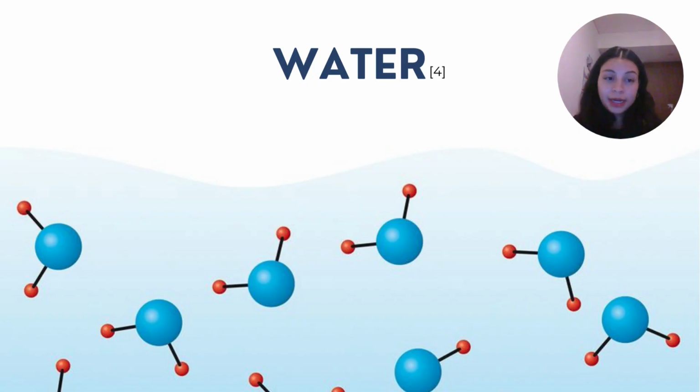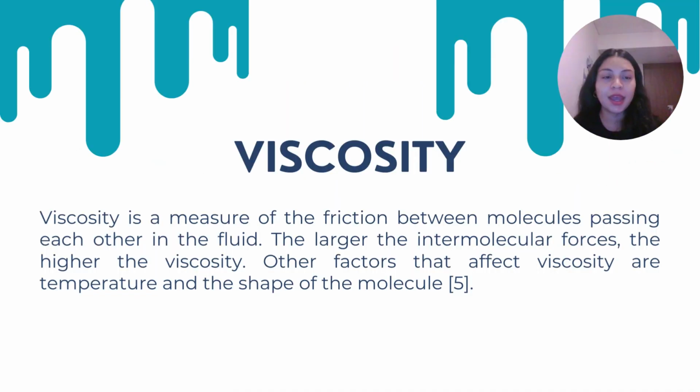The fluid that will be analyzed in this practice is water, which in its liquid state has different intermolecular forces, such as the van der Waals forces and Coulomb forces. And what will be measured in this practice is viscosity, which is the friction between molecules passing each other in the fluid. And the larger the intermolecular forces are, the higher the viscosity is. Other factors that affect viscosity are temperature and the shape of the molecule.